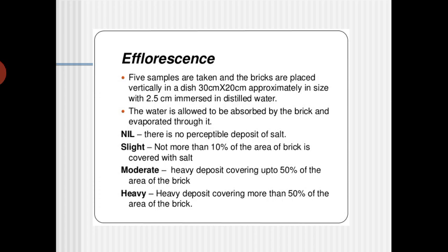You evaporate it with the help of heating equipment. Then you declare the result as nil if there is no perceptible deposit of salt, meaning there is no dust particles on the bricks.